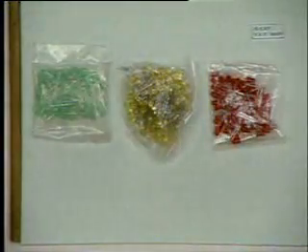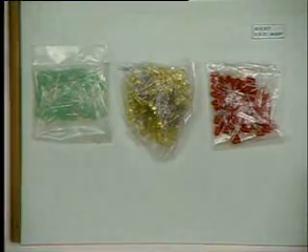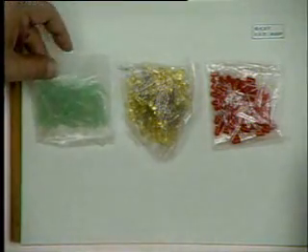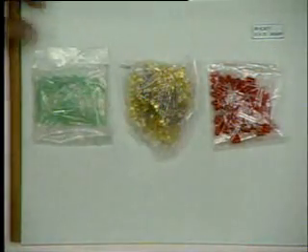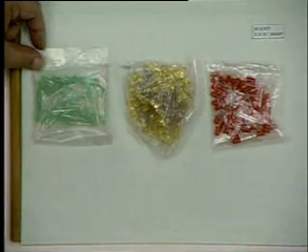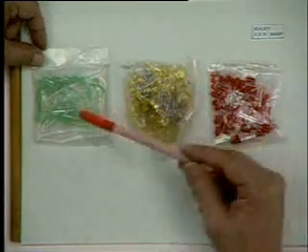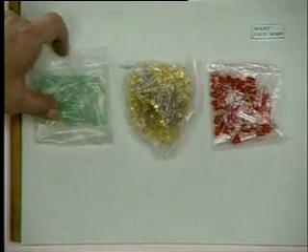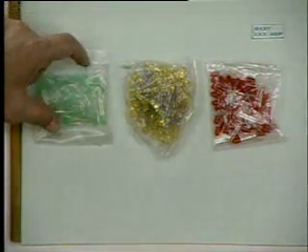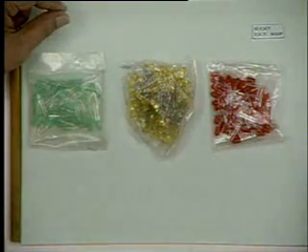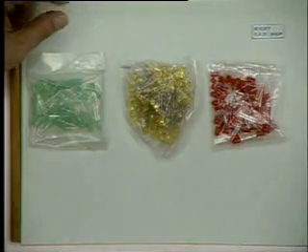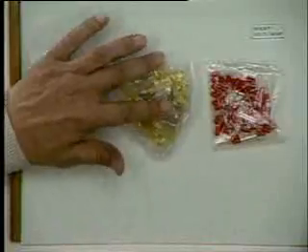And if I ask you what is the constituent of these LEDs, you should be able to answer. What are the green LEDs made out of? Yes, green will be gallium phosphide with nitrogen, because the band gap has to be large enough. Yellow will also be gallium phosphide with a slightly lower amount of nitrogen, etc. And the red?